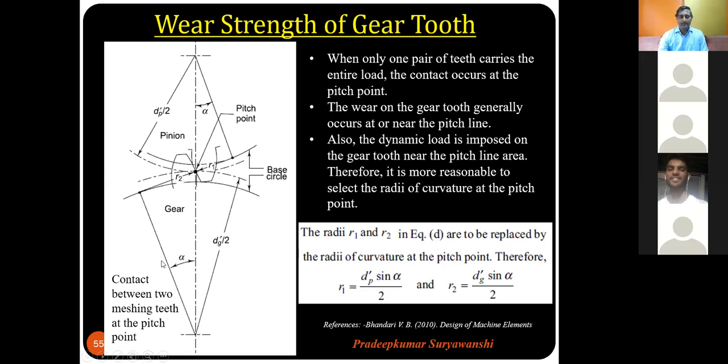That same angle will be between the vertical and the perpendicular line joining the center of this particular cylinder which we have assumed here and the center of rotation. We want to convert this R1 in terms of preferable dimensions, say the radius of the gear. So we make use of sin alpha equal to R1 upon this length, that is dp prime by 2.